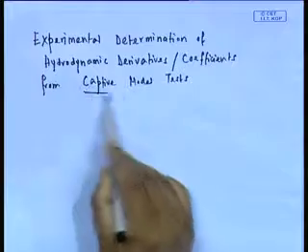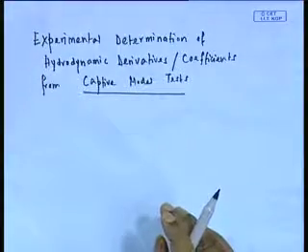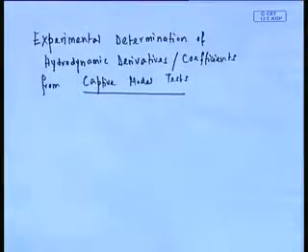Experimentally, you cannot go build a ship and then measure it. You might do that, but that would be after the design. The word captive model test, like the resistance test that you do, means that you are restraining the model in some motion. It is not a free running model, because you really cannot do that, as you have no control. In a resistance test, you hold it, allow only heave and pitch maybe, and then tow it. These are captive model tests.